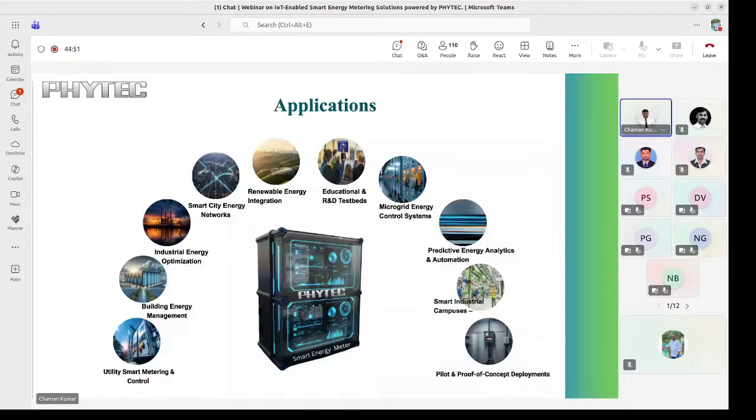And if you see the storage system, it has eMMC, and an SD card, a micro SD card slot, is also available, where the operating system runs. And the networking options are the backbone of the DCU. It has wired Ethernet, and wireless Wi-Fi also. A mini PCI slot is also there for a 4G module. And for wireless positioning and connectivity, it has RF connectors for GPS and LTE, and it has UART, 7 UARTs are available.